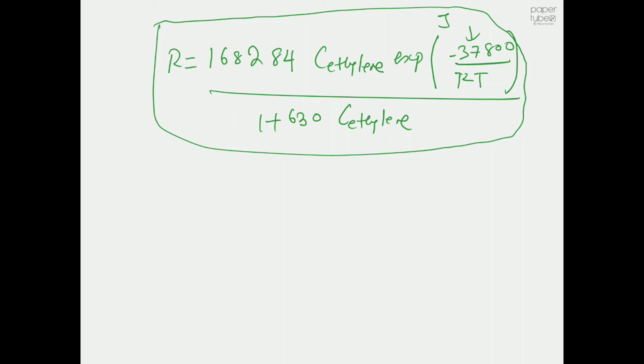In your final year design project, this is exactly what you are going to do. If somebody asks you to design a major unit operation, say a catalytic reactor, you have to go to the literature and look at what type of rate expression you need. If you're going to design a heterogeneous catalytic reactor, I think the Langmuir-Hinshelwood expression is the most widely used, and you are going to do exactly the same type of calculations.